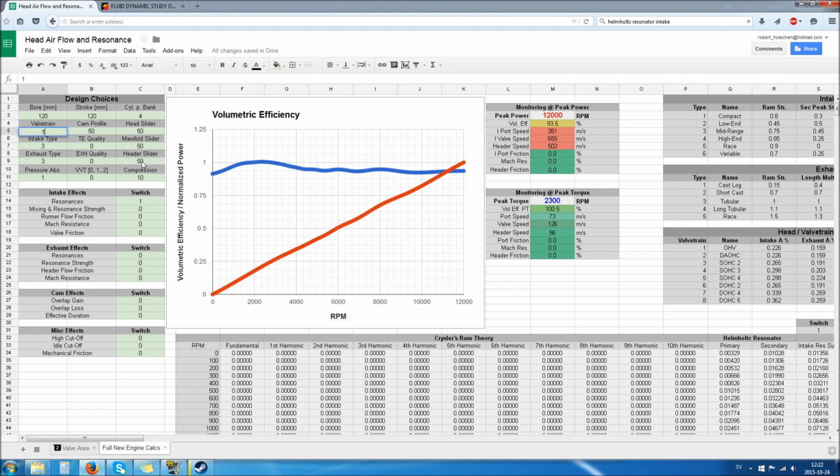And if we put on a pushrod head here, you will see that the resonances are moving even further down, and that is because of the design of the valves. You have a 2-valve setup, which means that you have less valve area there, which then again moves down the frequency of it. So this is all interesting and good and has a lot of emergent gameplay in it. So larger engines will naturally want to resonate lower, which makes them more grunty and less high-end, which is natural, you would say. Alright, so let's go back to a standardized 2-liter engine and take a look at what the other effect is.